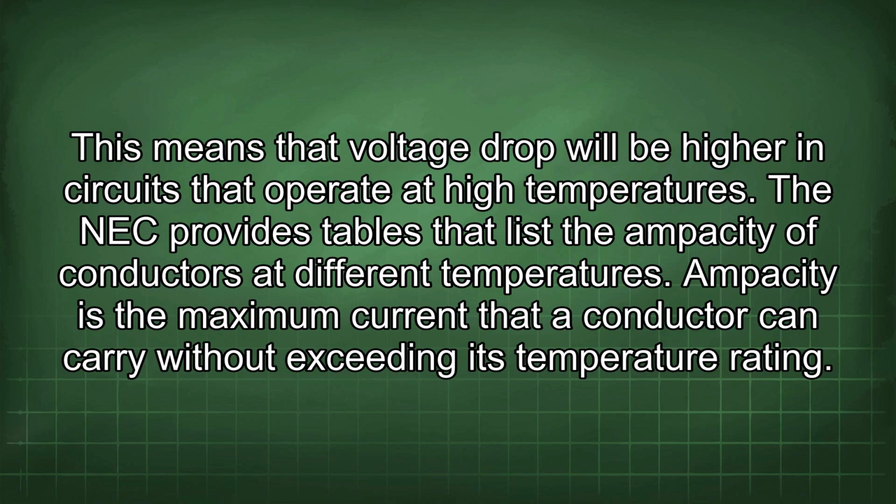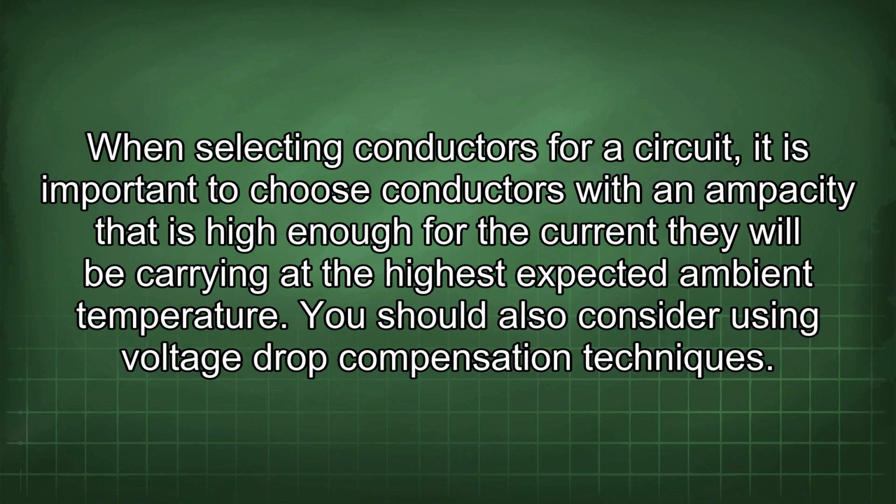The NEC provides tables that list the ampacity of conductors at different temperatures. Ampacity is the maximum current that a conductor can carry without exceeding its temperature rating. When selecting conductors for a circuit, it is important to choose conductors with an ampacity that is high enough for the current they will be carrying at the highest expected ambient temperature.